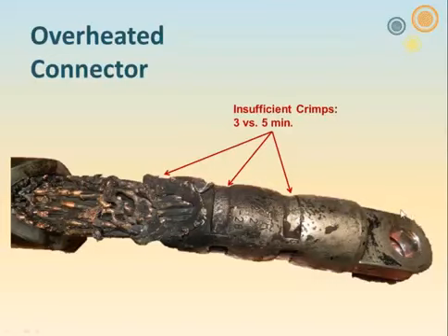So the heating was occurring over here, and right where you would expect it, this is the hottest portion of the connector between the end of the insulation and cable adapter and the end of the lug. That's the hottest part. It damaged the insulation in that area, and we had a failure, a puncture of the dielectric right in that area.